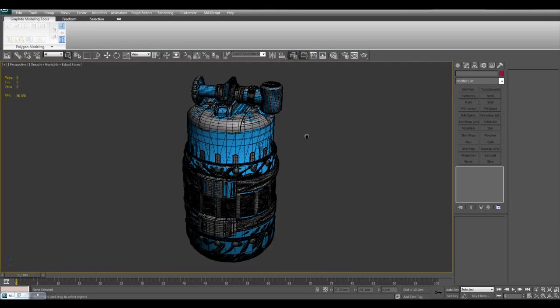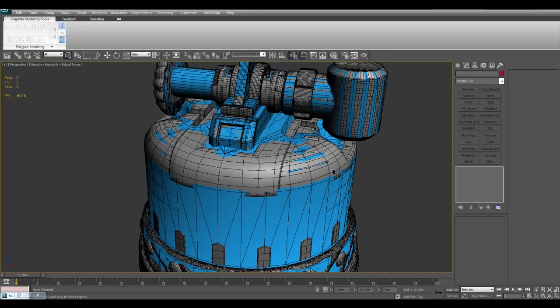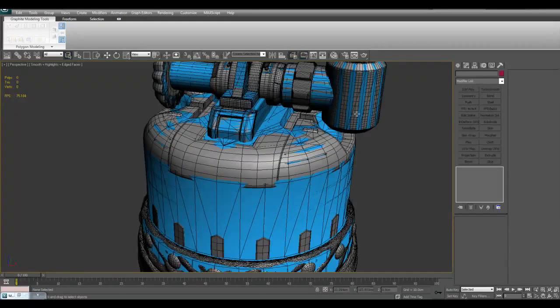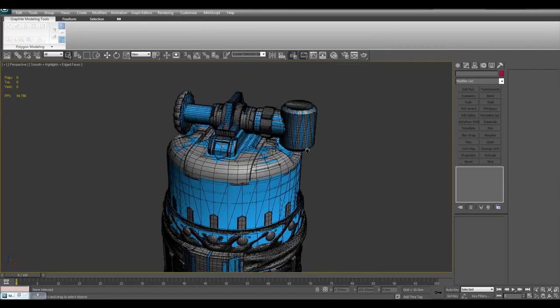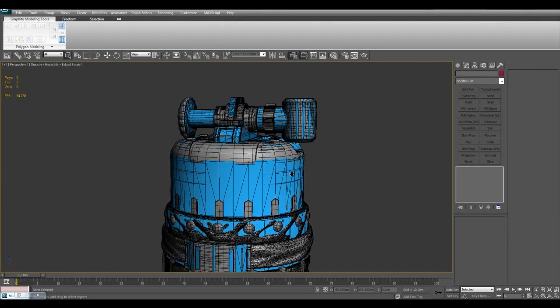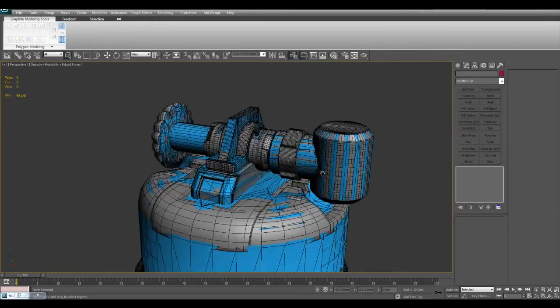In this video we'll continue learning about normal maps, and we will go ahead and unwrap the low polygon model, and we'll start baking the high polygon details into a texture map. So here is my low polygon on top of the high polygon. They're intersecting, which means that we have a nice match.